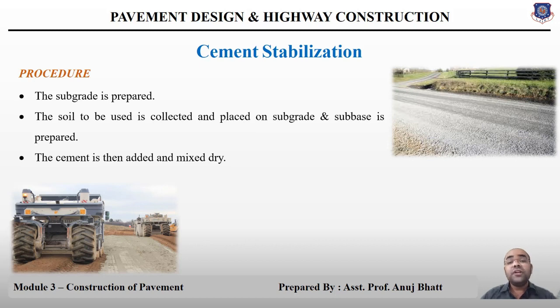Mixing should be done in two stages: dry mixing and second is wet mixing. The cement will begin to act on contact with water, which is why the water should be added to the dry mix at the last moment before the compaction in order to keep the time before it is used to a minimum.